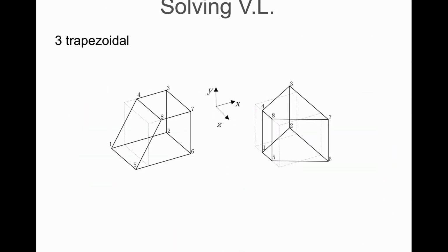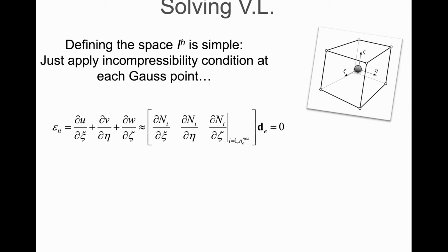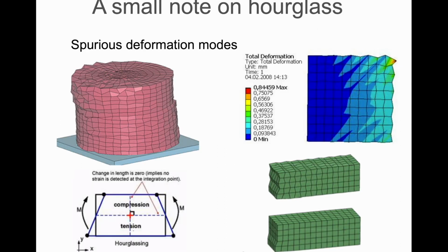Now I'm coming back here to explain the downside of reduced integration elements. So we are under-evaluating the stiffness of the element. So what you're going to see is sometimes you can have a deformation energy without any displacement. So there's something called hourglass patterns.